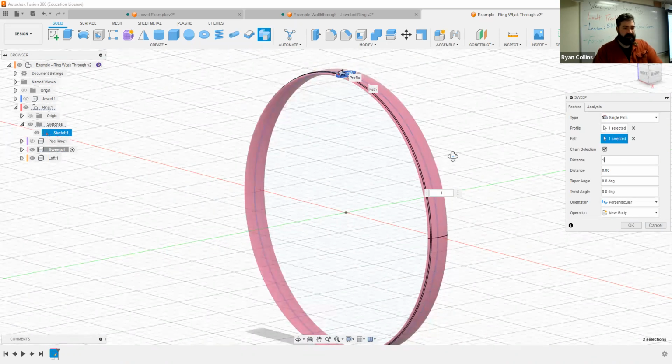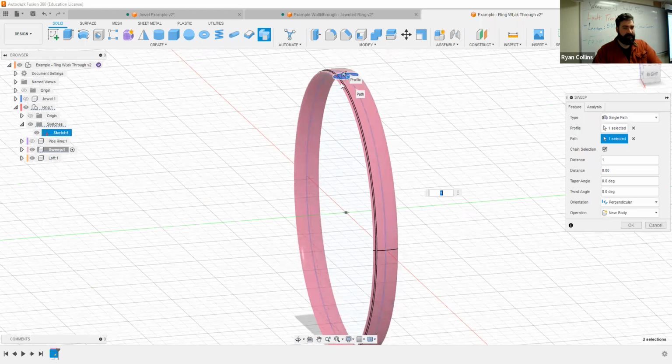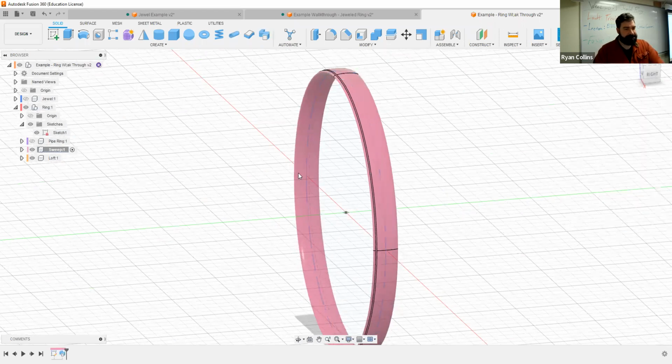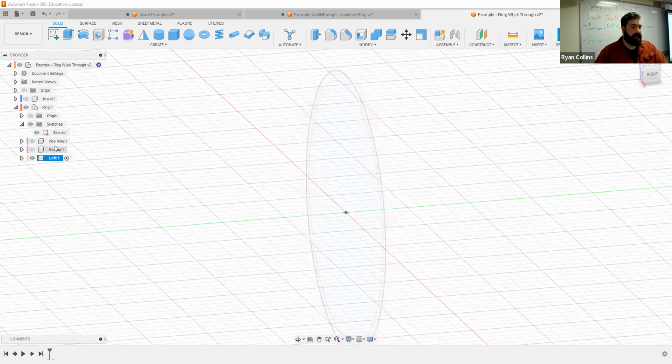So that can be a very, very simple ring. You can, of course, play with the profile. This is a very narrow one. Play around with it that way. Jumping to loft, exact same thing. And just so you know, because I created the profile sketch on the general component outside of any of these selections, remember it can be shared between them. It's only the actual profiles that are specific to any component here.